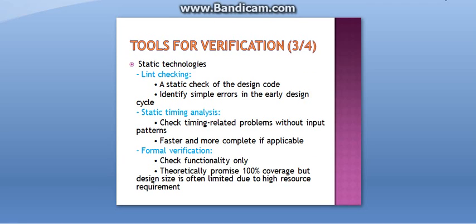Static technologies are lint checking. It is a static check of design code that identifies simple errors in the early design cycle. That is, it avoids error code that increases design iteration. It checks for built-in or user-specified rules like testability checks, reusability checks, etc. Static timing analysis, that is STA. STA is a method for determining if a circuit meets timing constraints without having to simulate. It checks timing related problems without input patterns.